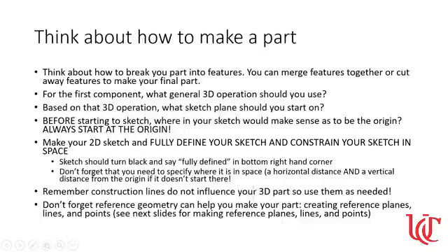Okay, so for the first component of my part or feature of my part, I need to think about what 3D operation I am going to use. Am I going to use extrude, revolve, loft? Based on that 3D operation, what sketch plane should I start on? And I should think about these before I start my sketch.